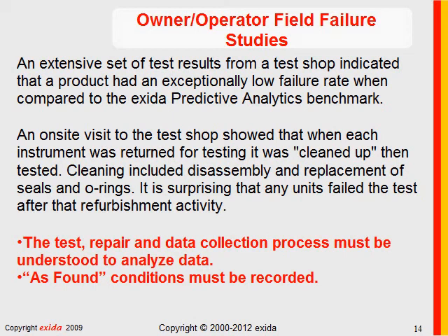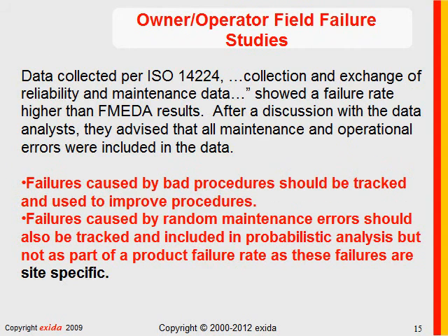Why? An on-site visit to this particular test shop showed that when each instrument was returned for testing, it was cleaned up. And their definition of cleaned up is effectively an overhaul. It was disassembled, cleaned, replacement of seals and O-rings. In fact, I was surprised that any of the units failed after this particular refurbishment activity. Bottom line is, anyone who analyzes data must understand the test, prepare, and data collection process. As-found conditions must be recorded. Obviously, they were not recorded in this case.